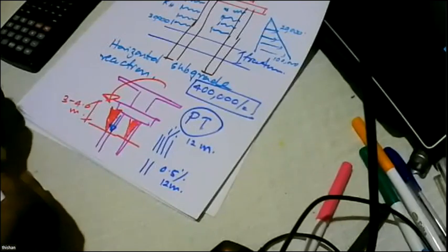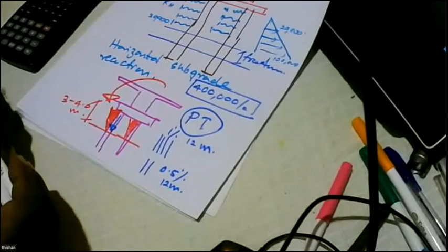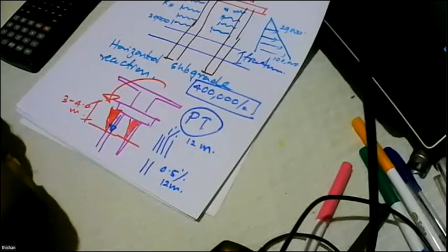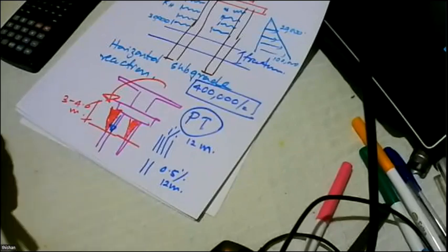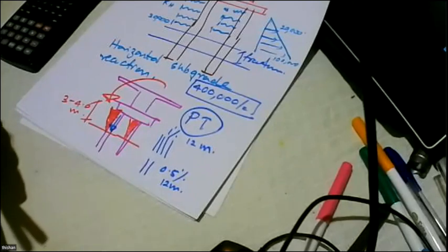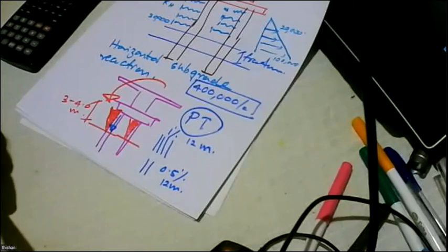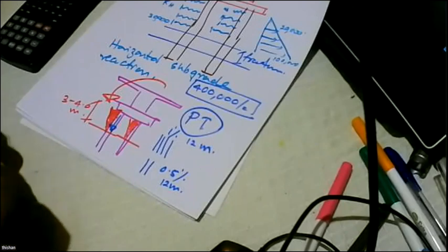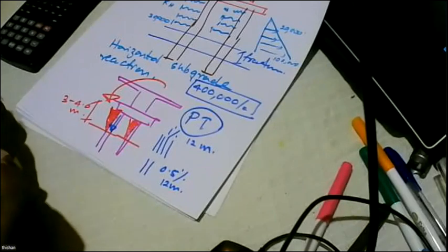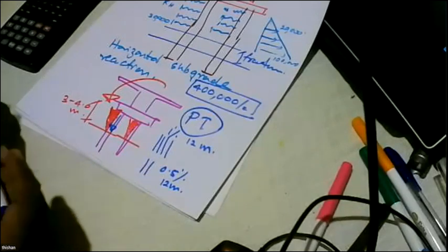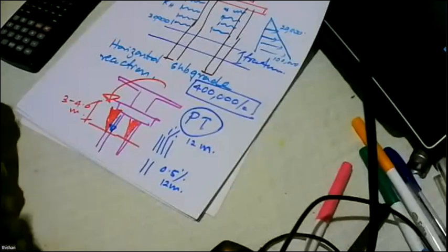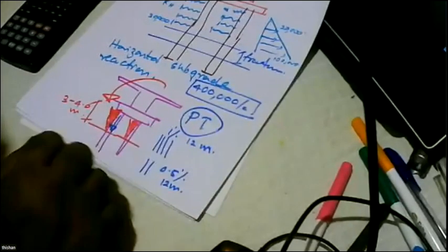So, in the case of piles, we need to have a certain amount of minimum reinforcement, otherwise you don't get sufficient strength in the piling cage. So you can't maneuver the piling cage unless you have enough reinforcement. Because of that reason, 0.5% might be a good idea. Whereas in the upper part of the pile, you can go for 0.8 to 1%. And I have seen Road Development Authority engineers like 1% reinforcement in the piles. So that's a kind of information I can give you.